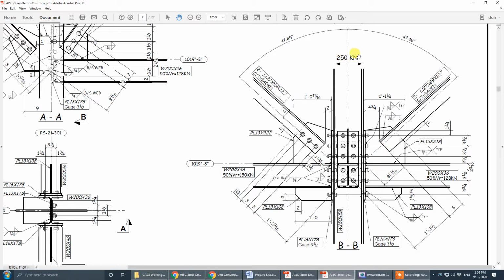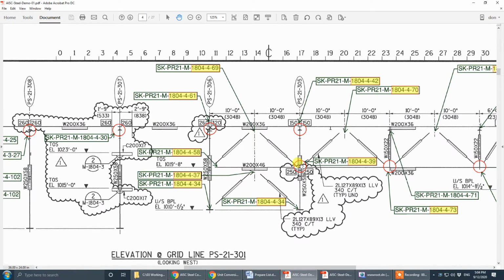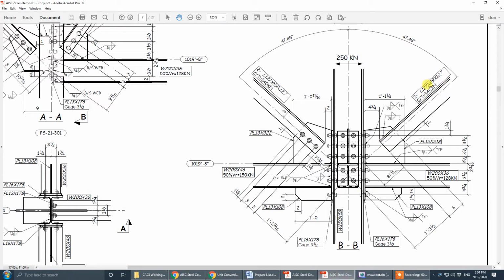you see this pass-through force. We do the vertical brace of this one. So on the elevation view, we do vertical brace of one side, right side, and left side separately. So we do the vertical brace on this one, assuming there's no left side. We do the vertical brace of left side, assuming there's no right side.